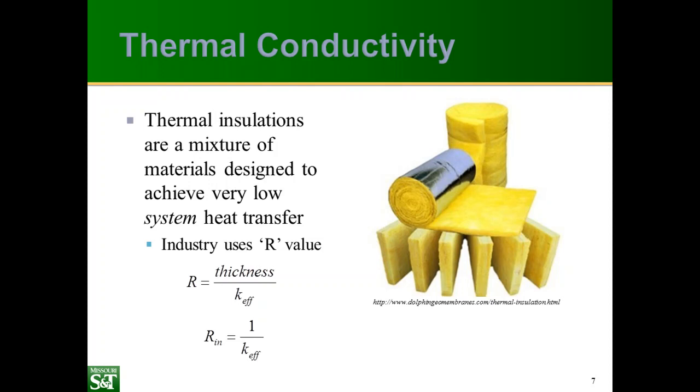Fibrous insulations have small particles or fibers. They're very porous. Cellular insulations have small open or closed cells. They're usually in the form of boards, but they can also be foamed or sprayed in place, so that spray-on insulation is an example of cellular insulation. They tend to be very low density and low heat capacity and have good compressive strength. Granular insulations have small particles of inorganic materials. So there's a whole bunch of different kinds.